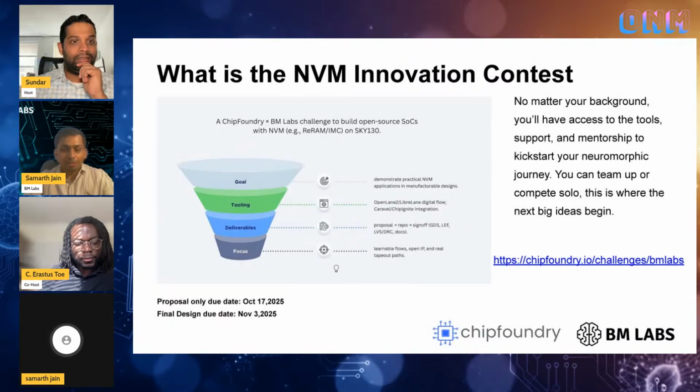So just write a Python behavior model of your IP, right? Or write a block diagram. Okay, first you can start with the block diagram. Give it to GPT, write a Python behavior model, and then check that Python behavior model first, whether it does what you need mathematically and logically. Then maybe convert it into simple behavior level Verilog. Simulate that behavior level Verilog, which is mostly represented by C programming or Python programming, right? There is no RTL level, there is no transistor or IC design in behavior level. It's just maths.